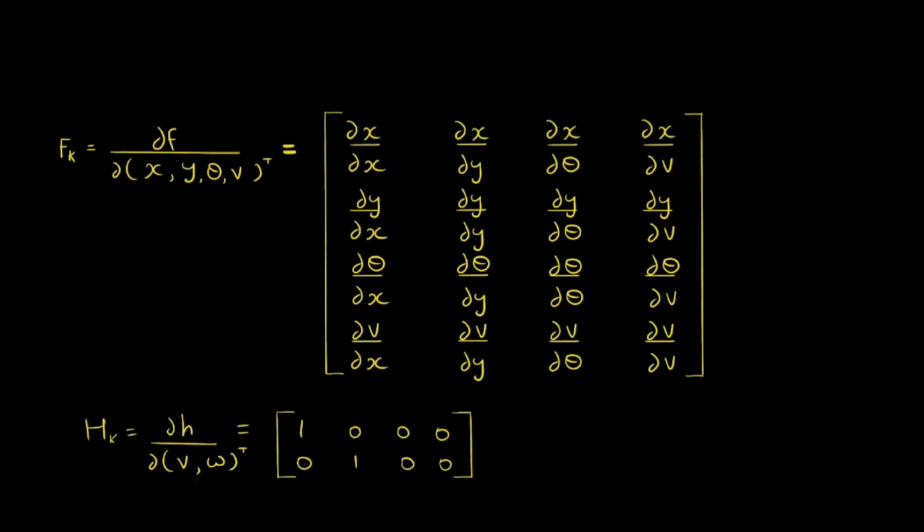And we also consider a measurement model. In the measurement model, what we consider is that there is no transformation currently taking place. We are considering directly what is coming in from the GPS or IMU. There is no transformation here, so if there is no transformation, we consider it as the identity matrix.